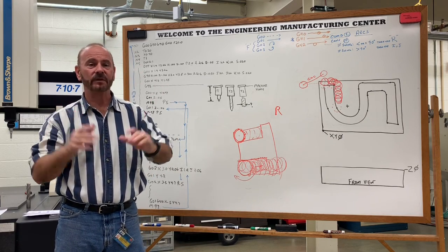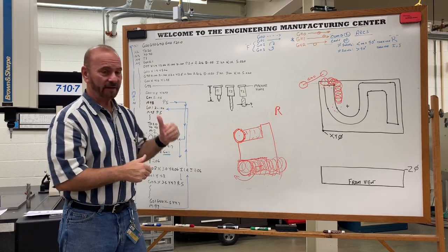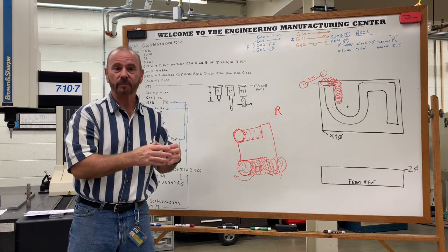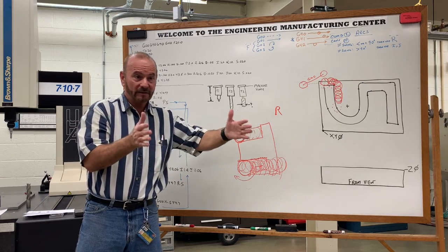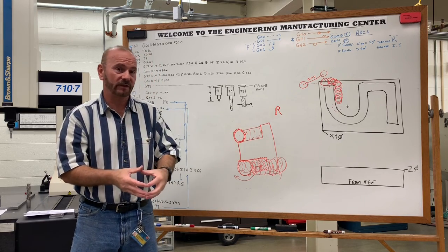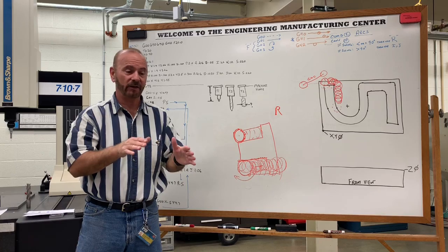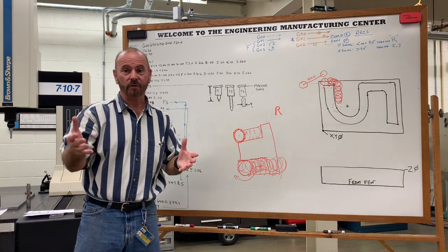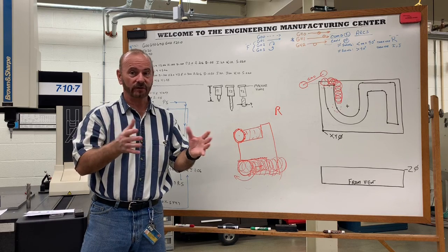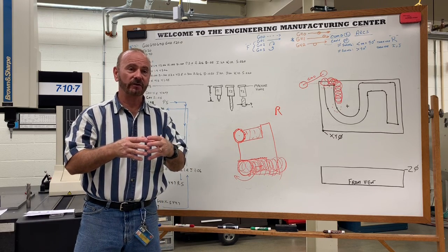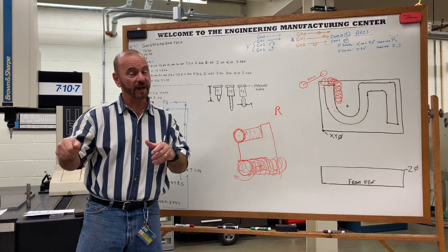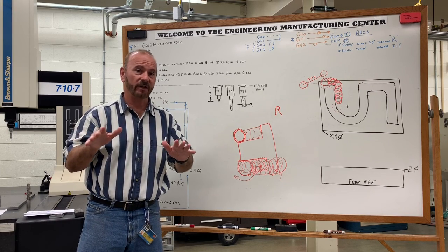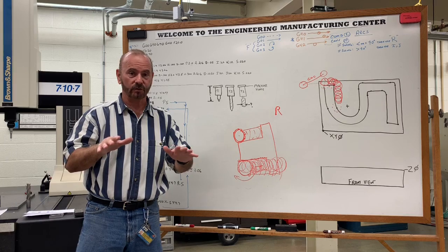Well, the same thing happens in the material. That baseline that you just calculated is under perfect conditions, meaning that you've got the sharpest cutter, using the best type of machine in the most rigid setup. If any of those conditions vary, maybe your part's got some thin areas, or it's hanging off the vise a little bit, or your machine's not quite that new or tight, those are going to cause you to have to slow down just like you would on the highway. So you adjust the feed rates and the RPM in order to do so.